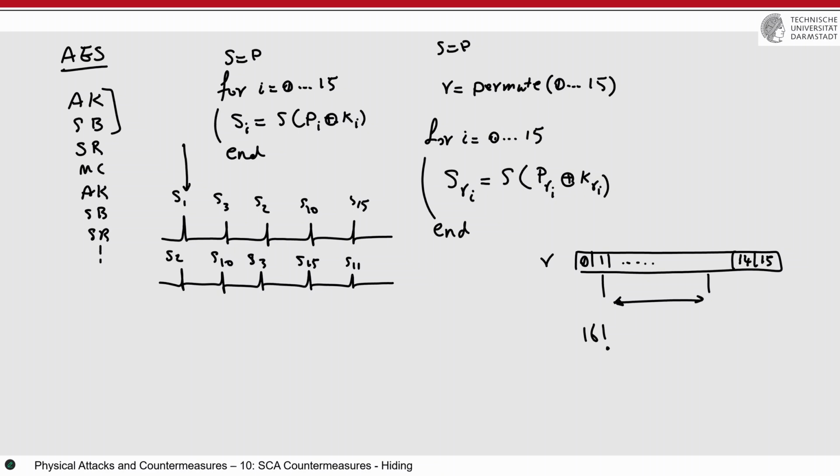But for example, you target the first S-box. You target K0. But then it doesn't necessarily happen here, because S0 is sometimes processed here, sometimes here, sometimes here, sometimes here, and so on. In different places, different clock cycles. If you have the full entropy, then in 1/16 of cases, S0 is processed there. Then here is S0, but not always, because there is another clock cycle where, for example, S0 is processed here. Then the target that you want to exploit is there, but plus 15 other cases that are completely not considered in your attack. Then it's a high level of noise.